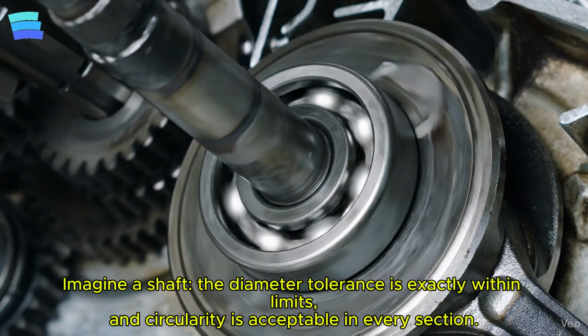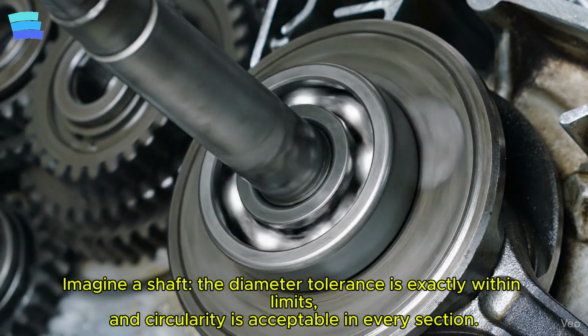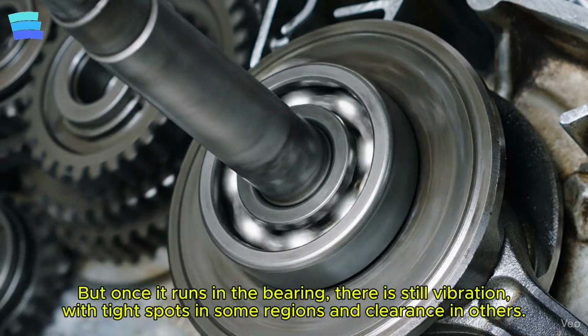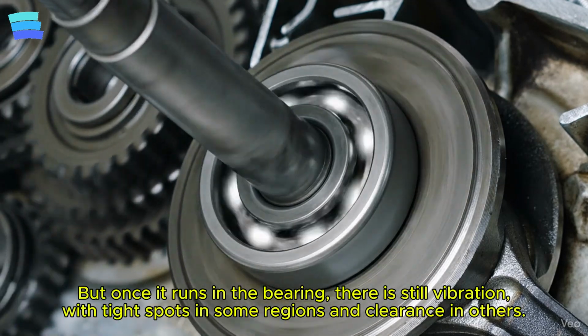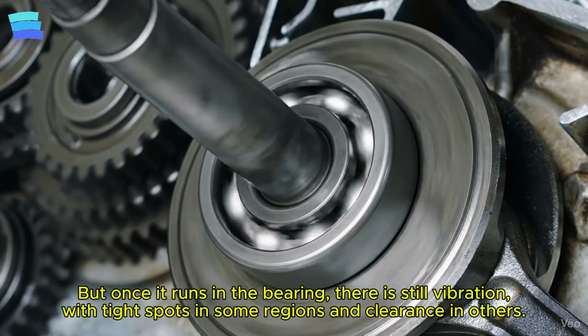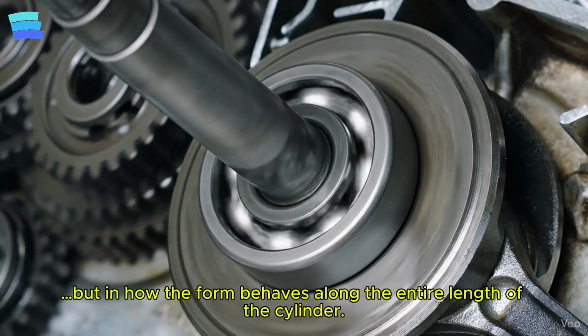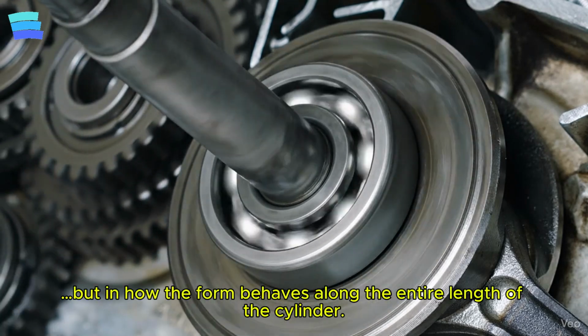Imagine a shaft. The diameter tolerance is exactly within limits, and circularity is acceptable in every section. But once it runs in the bearing, there is still vibration, with tight spots in some regions and clearance in others. What is the problem? Not in the individual sections, but in how the form behaves along the entire length of the cylinder.